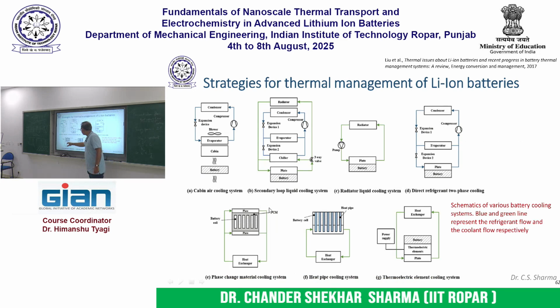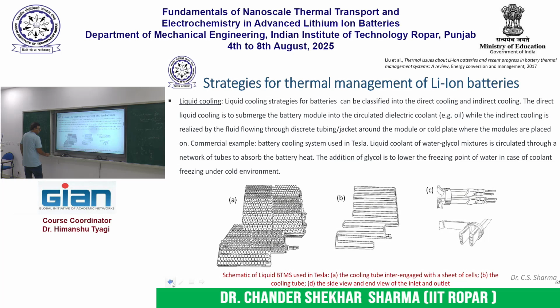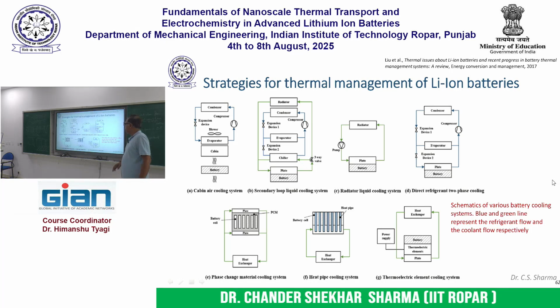So here you have the battery cells, and either these battery cells can be directly immersed in cooling oil, which is dielectric, or you can circulate water, you can have indirect cooling. So this is a schematic from one of the patents filed by Tesla many years back, and they have made this patent public. Okay, so you have here these cooling channels where liquid coolant is being used to cool the battery pack. And then other strategies can be used.